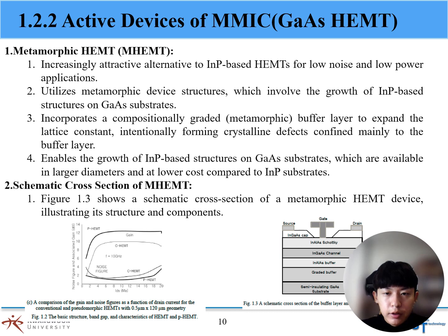This part is the metamorphic HEMT. It is an increasingly attractive alternative to InP-based HEMTs for low noise and low power applications. It utilizes metamorphic device structures which involve the growth of InP-based structures on GaAs substrates. It incorporates a